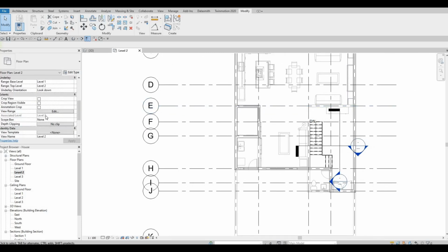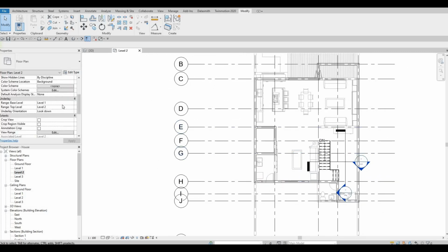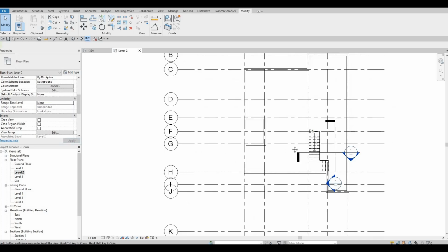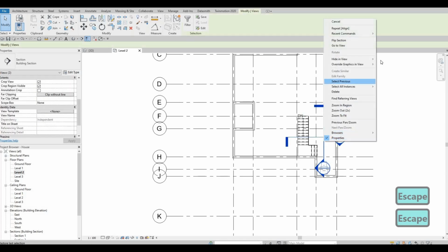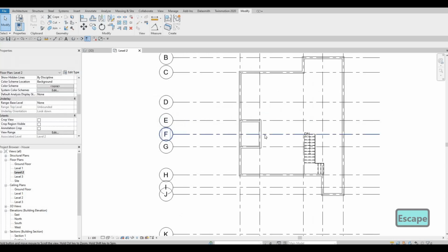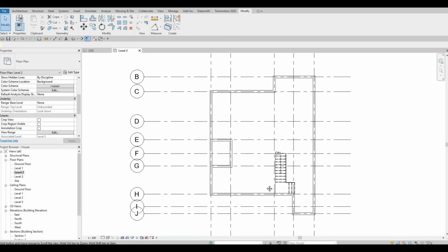We can turn off the underlay now. Later on we could turn it on, because we could basically CS a lot of stuff that are down there already. So here I'm going to put it to none and click on apply, and then here we could hide it for now, hide element, and then if we want to show it again, we could just reveal it later on.